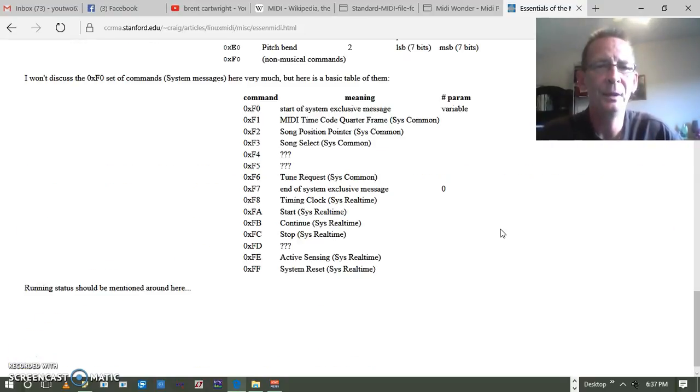All right, the basic functions of the system messages, as far as I can tell from my understanding and from looking at them a little bit: you have the start of a system exclusive message, telling you that there's a system message coming, or it's the start of it. A MIDI time code that has 24 pulses per quarter note to set the system time, so that there's timing and a time code set with the actual file.